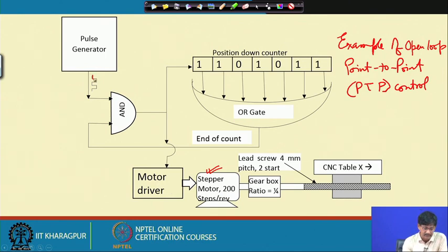See here, pulses are coming out. Let me accentuate these pulses. So, voltage pulses are being developed by the pulse generator, and it is led through an AND gate, and ultimately it reaches the motor driver. So, per pulse the motor will be rotating by one step, okay, and it covers one full revolution. That means this shaft goes round once, okay, this is the output shaft of the motor. This goes round once for 200 such steps.